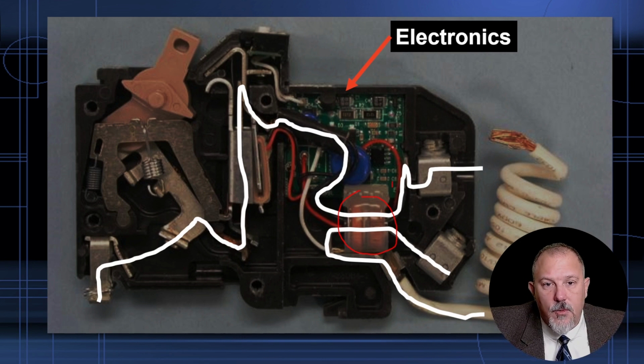And you'll see there's a red wire right here, and I believe there's a black wire in there somewhere as well, that basically brings the current output to this motherboard, to this circuitry, so that the brain can tell the circuit breaker when to open. And you'll notice right here, there's a red conductor and a black conductor, and there's a plate, and there's a coil around this plate.